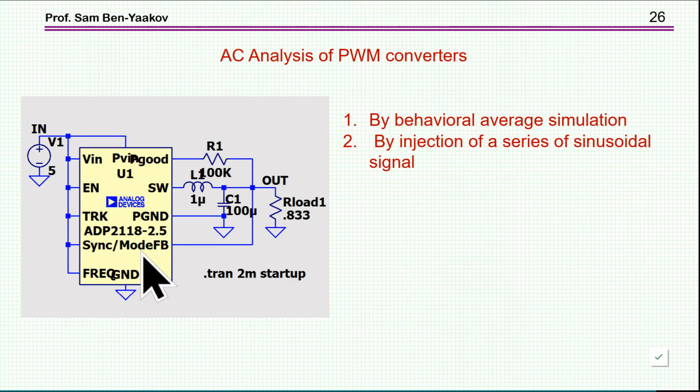Now what about PWM converters or some other complex units? In, say, LTspice, you have the model of the converter, and in fact they have the so-called jig, or the whole circuit, a demo circuit that you can get out and run. It will run very nicely in the proper analysis, but this is not compatible with AC analysis. You cannot run it in AC analysis. I mean, you can run it, but it'll give you some nonsense, okay? So, what can you do?